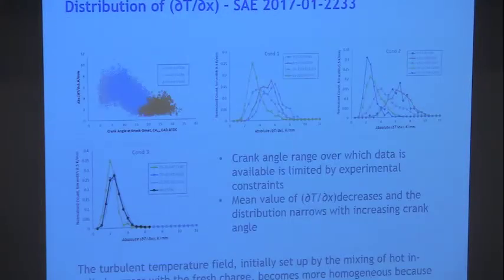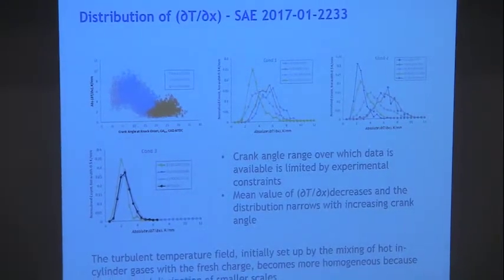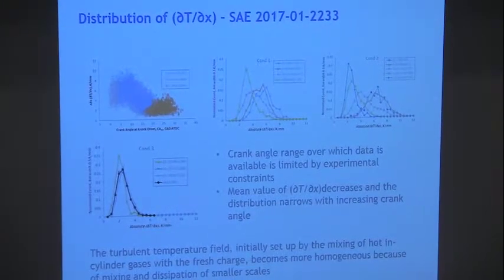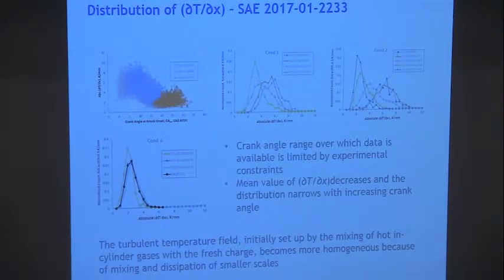I won't go into this because it's a bit complicated. You remember I told you that we make measurements in 3 different operating conditions. One was the boosted condition, and the other 2 were non-boosted conditions. That allows you to go to different areas of crank angle and pressure at which knock occurred, and essentially allows you to estimate how this temperature gradient changes for each condition. And it makes sense. Anyway, let's leave that, and now I'll come to super knock.